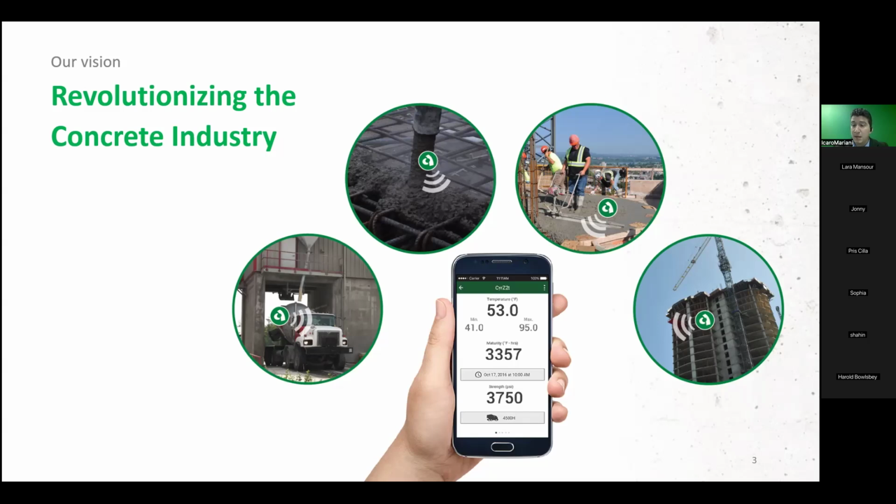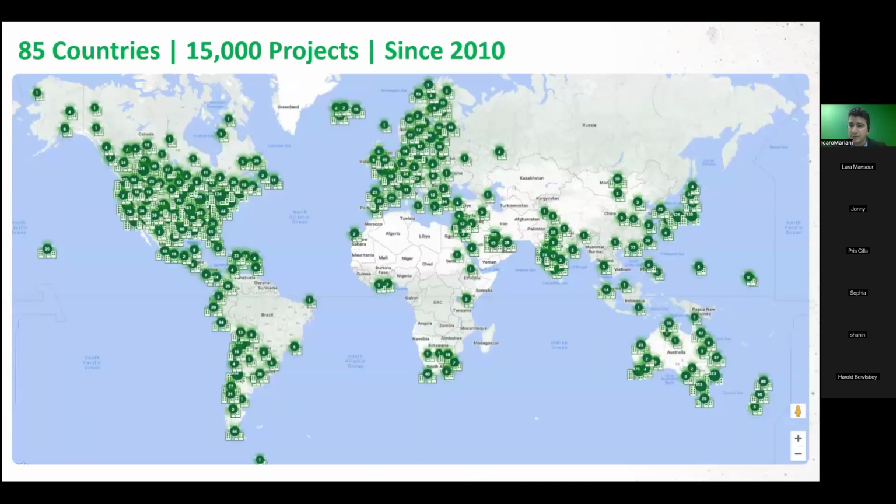Very cool. Imagine that you have different mix designs, and then you have a patchwork in a viaduct where you're gaining strength in 3 or 4 hours. Knowing that start time is very beneficial. So that data analytics and the machine learning that came out of the thousands of data points we acquired in the past years actually helped us succeed on that front. Love it.